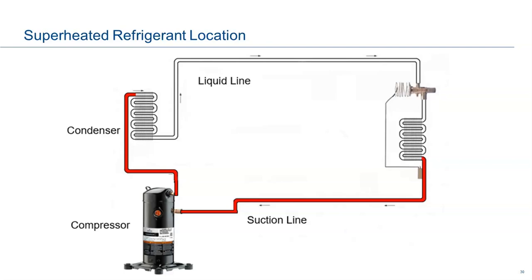What they have found over the years testing compressors for overheated compressors is the hottest point inside a compressor, okay, inside the scroll set, leaving there, we lose somewhere between 50 to 75 degrees heat, okay? We lose 50 to 75 degrees heat from the hottest point of our compressor to 6 inches down our discharge line. So let's just say the worst scenario is 75 degrees. If we take that 75 degrees and add it to that 225 degrees that we never want to be hotter than, we come up with the temperature of 300 degrees.